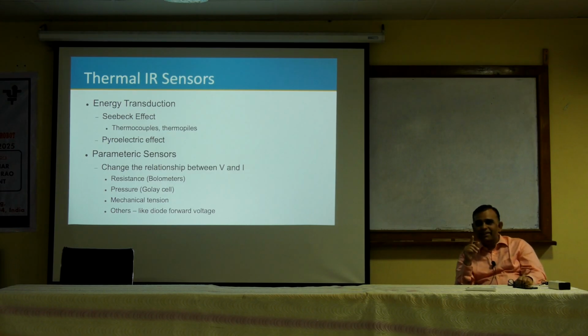It's the I naught term which appears there. That is heavily temperature dependent. Okay, so I naught times e to the power voltage something. We will see it's not a very easy relationship with temperature. As a rough rule of thumb, we say for every 10 degrees Celsius it doubles. So it's an exponential kind of change, but that's a rough rule of thumb. It also depends upon what type of diode you have, what material you have made. Okay.